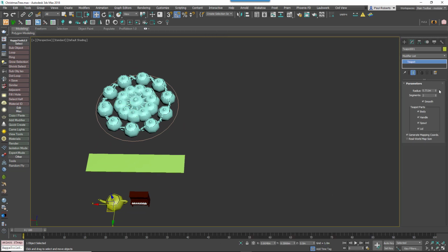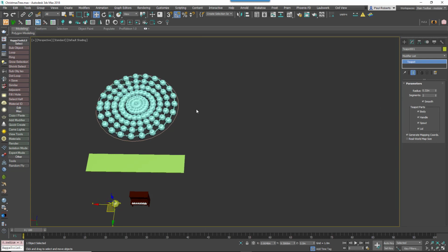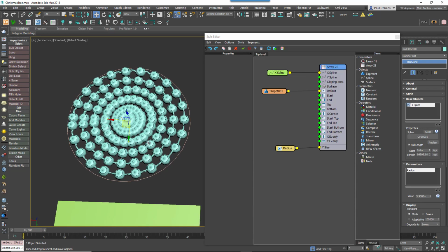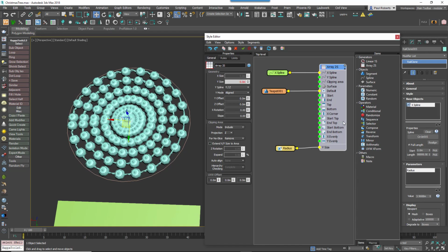There is a little known mode in RailClone that allows the segment count of each row in a 2D array to be calculated independently. To enable it, you simply go to the generator's properties and change General Y mode to Free.